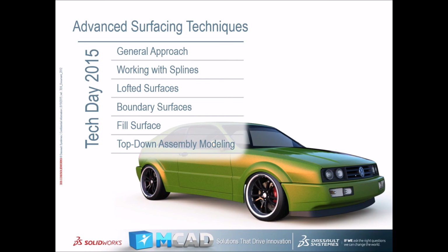The fewer points that you have, the smoother the curve is going to be. And remember, we now have two different curve types in SolidWorks. We have the original B-spline, but we now have that new Bezier curve. And then the difference between lofts and boundaries: lofts have a unique centerline ability, but they lack the control at the endpoints and the ability to control the geometry from the surfaces around it.